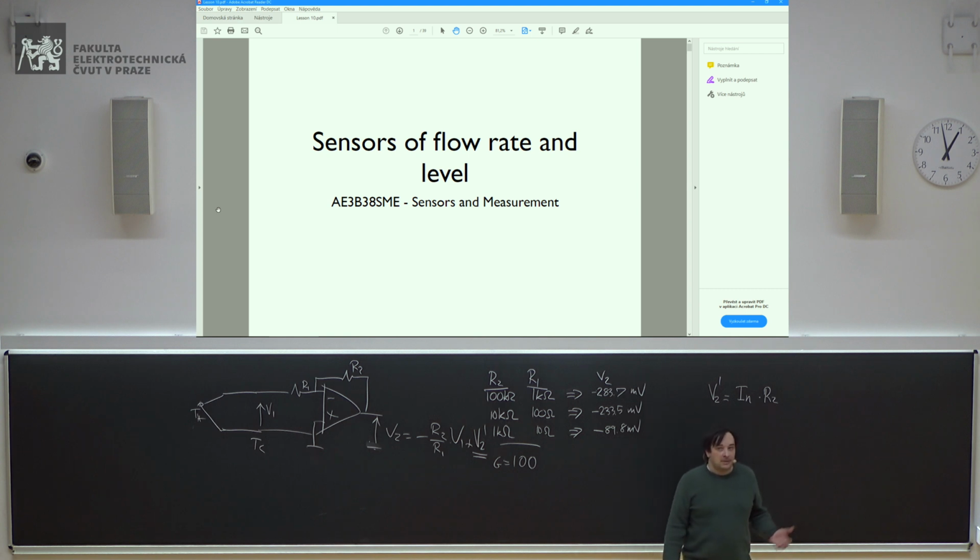Now, technically speaking, it is true that you have a larger component in the output given by the bias current if you have a bigger resistance R2. But is this the cause of the difference we observe at the output? And here's the point. The phenomenon itself is true, but that's not enough. You must prove that this phenomenon is able to justify what you observe here at the output. So let's put down some numbers.